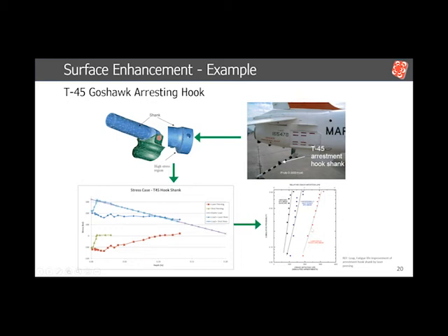And as Michael had indicated in the graph, the prediction of life certainly improved the capability of that part. But again, it's making sure you really understand the application of the residual stresses and modeling that component with a finite element model analysis to really understand the impact between the operational loads and the stresses that you've imparted.